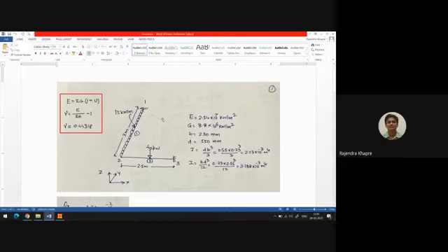Especially in case of grid, the geometry of the grid is defined in the X and Y plane. If you see from the top, you will see a grid of X and Y. Whereas if you see the loading part, the loading is parallel to the Z axis. In terms of SAP, you can say the direction of the loading is in the direction of the gravity.